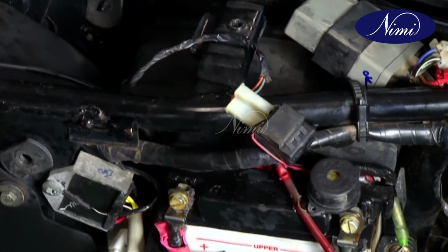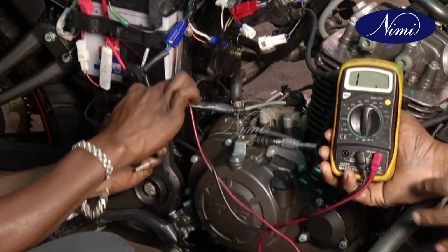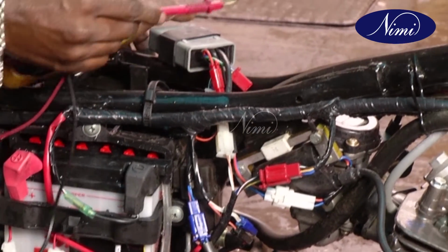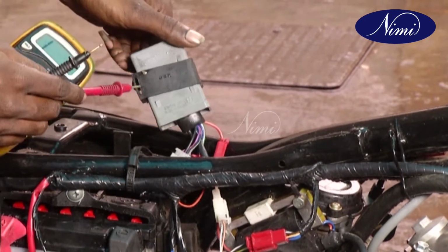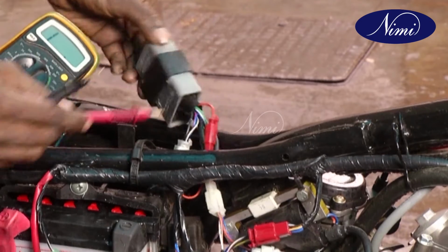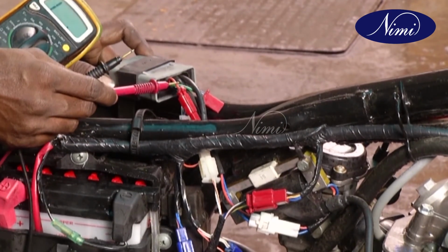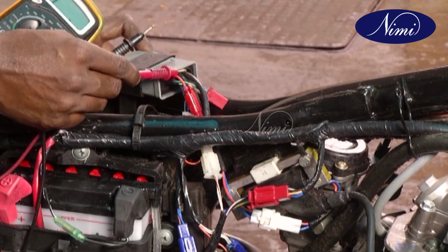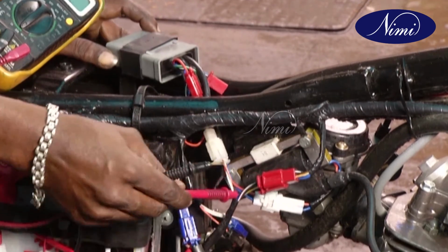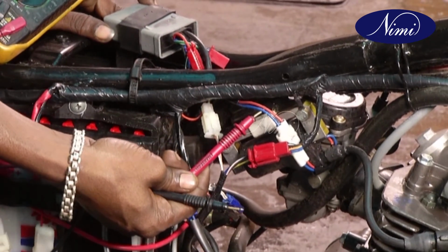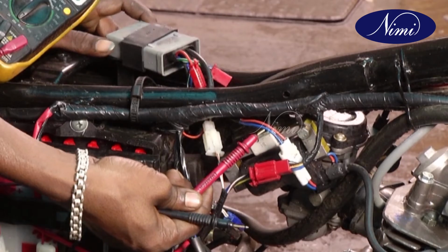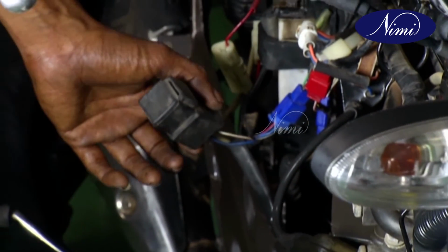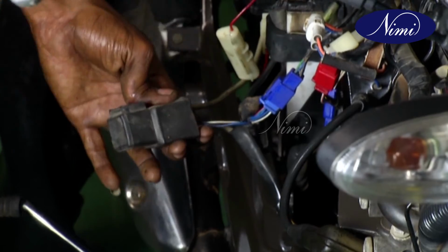Check voltage in the coil ignition circuit, magneto assembly. Check the connectivity between battery and CDI, capacitor discharge ignition unit, using a multimeter and check for any faults like discontinuity, open connections using ohm meter, the magneto assembly with CDI unit, HT and LT coil and magnetic pickup.